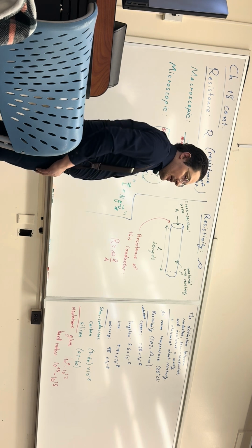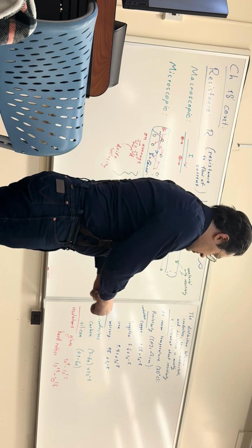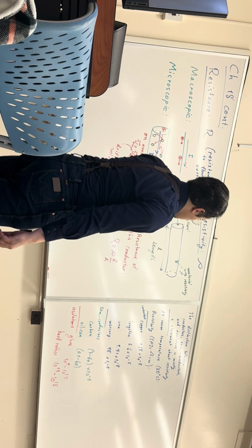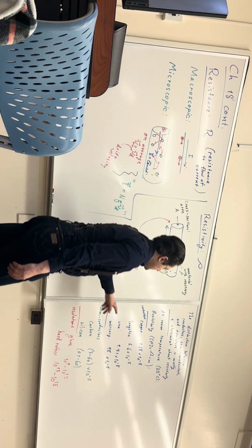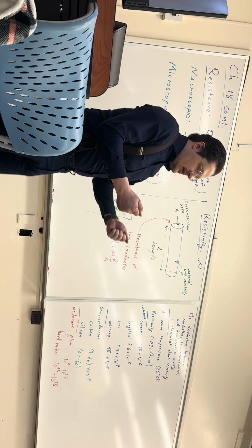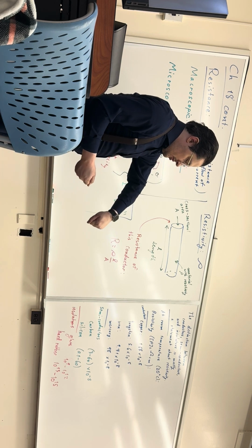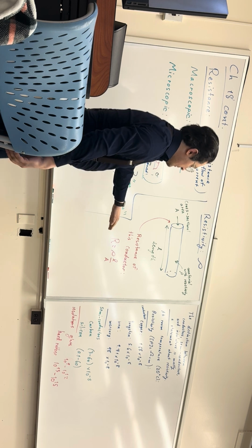But you can in fact measure, if I have a long length of copper wire, you can literally measure the diameter, you can literally measure the length, you can know what the resistivity is for copper, and then you can check that that's true by taking an ohm meter and putting one end on one end of the wire and one end on the other end, and you will see that it has the correct amount of resistance.